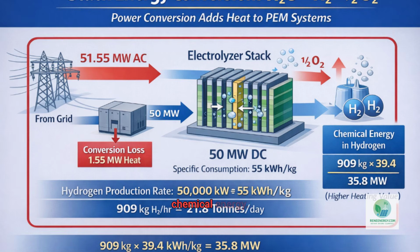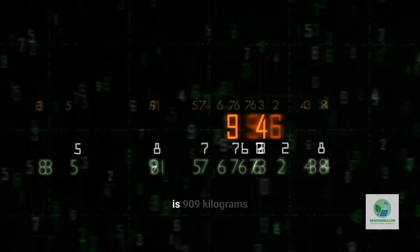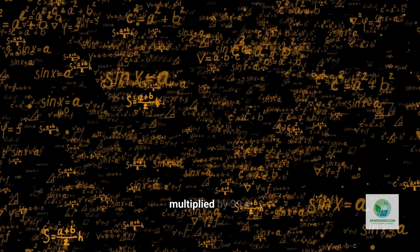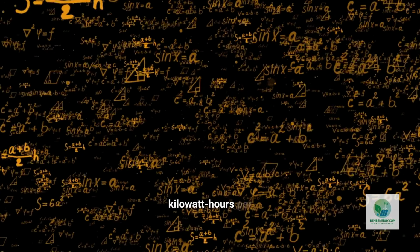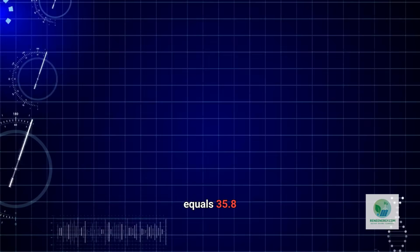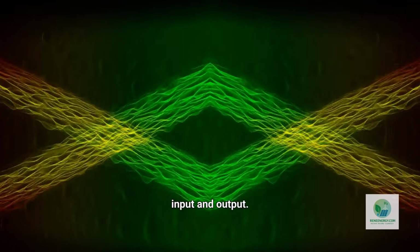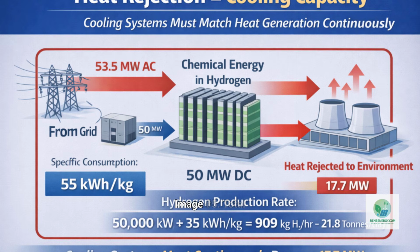Hydrogen contains chemical energy. On a higher heating value basis, hydrogen stores 39.4 kilowatt hours per kilogram. Therefore, the chemical energy leaving the plant per hour is 909 kilograms multiplied by 39.4 kilowatt hours per kilogram, which equals 35.8 megawatts of chemical energy. At this point, we must reconcile input and output. Now proceed to image number 5.